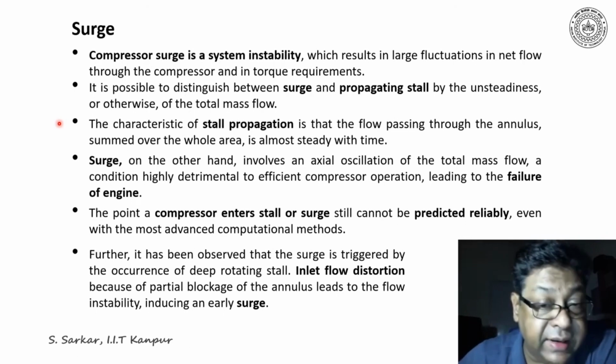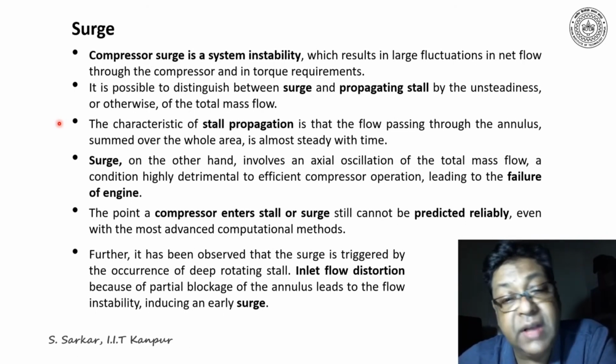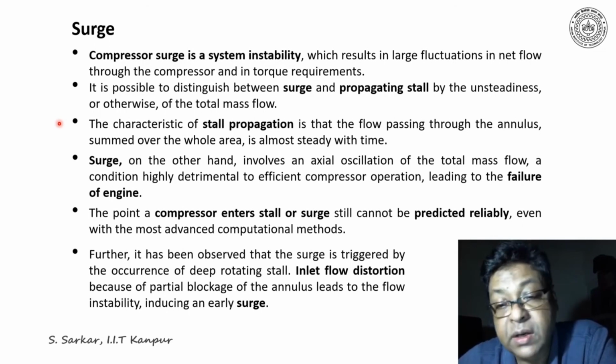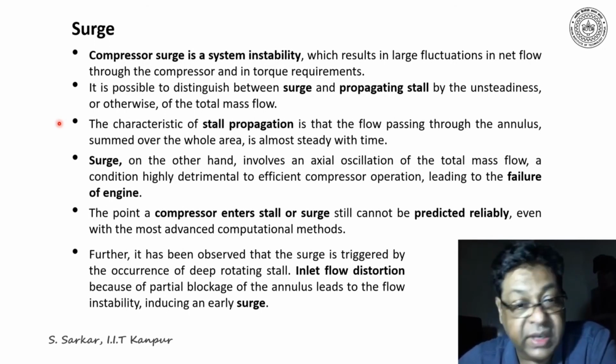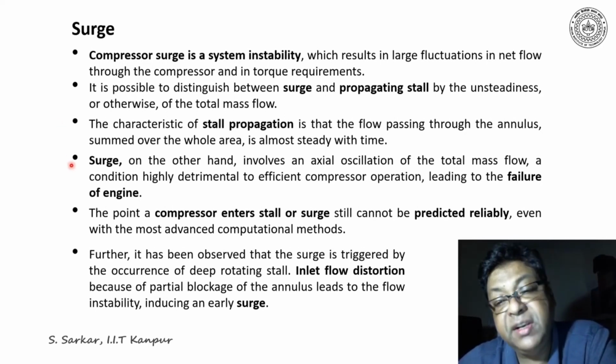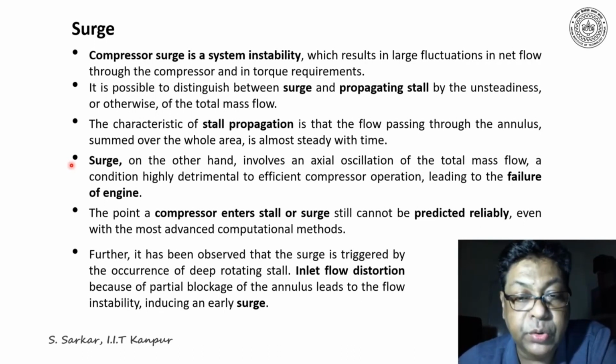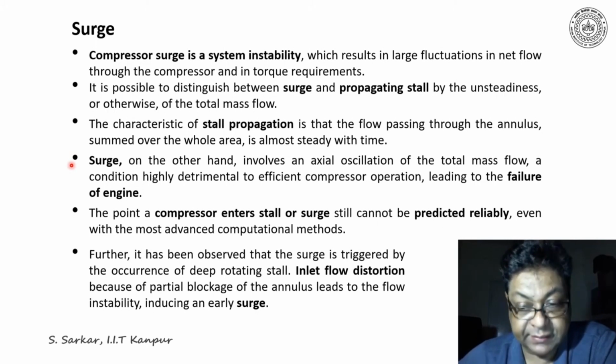Surge, on the other hand, involves an axial oscillation of total mass flow, a condition highly detrimental to efficient operation of the compressor, leading to the failure of the engine.